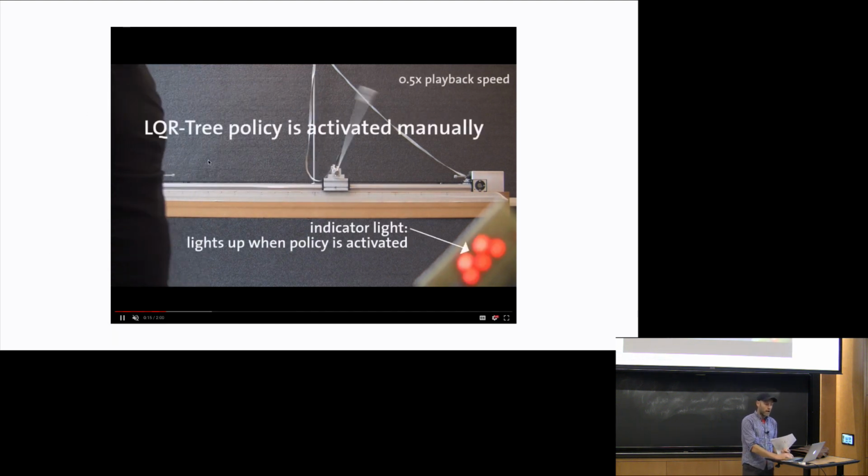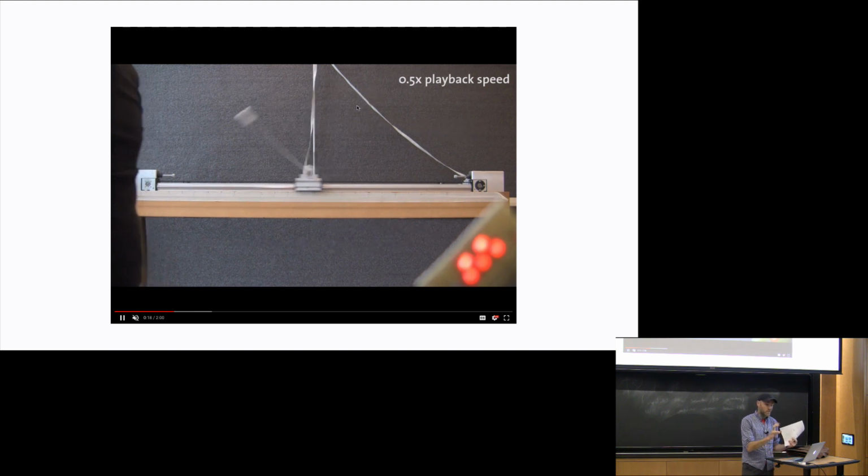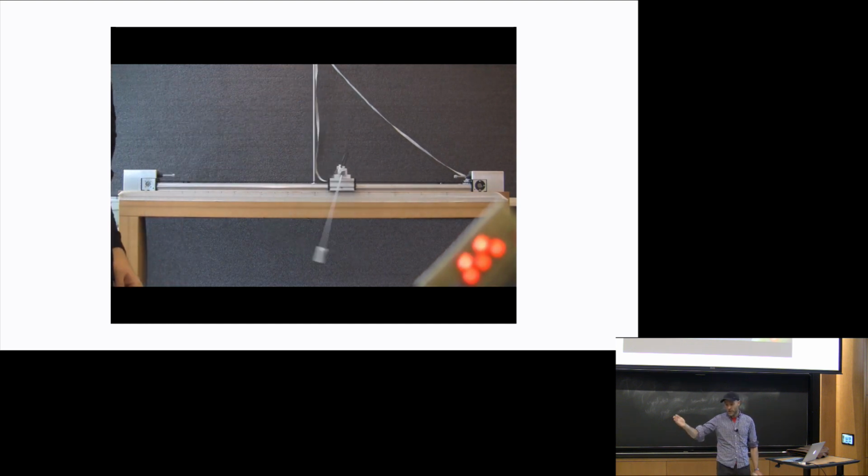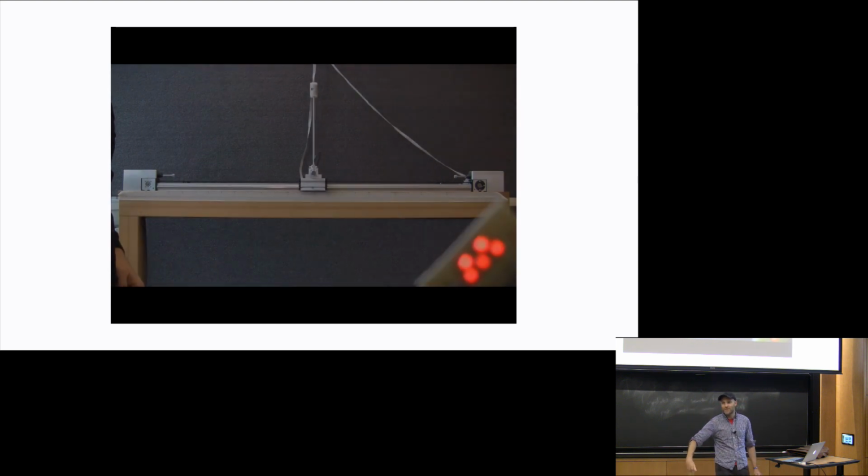And I actually don't know a better way to write a global stabilization for this cart pole, given that it has these hard limits on the x-axis, in order to get what we think is pretty much every initial condition possible for the cart pole to eventually get back up to the upright. I guess there are more conservative ones. If you're close to the rail, you could always just let it fall, wait till the system comes to rest, and then slowly go to the middle, and then do your thing from the middle, as long as you don't hit the rails. But I guess maybe that's less satisfying.